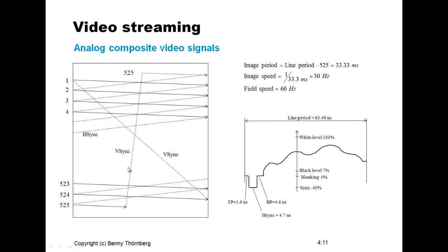During all of these transfers there is a blanking, which means that you are cutting off the video signal during this time, and there is just the black level on the video signal. And after the odd field, the camera continues to sense and send all the even lines until it reaches the end of the sensitive area and starts again with the odd field.